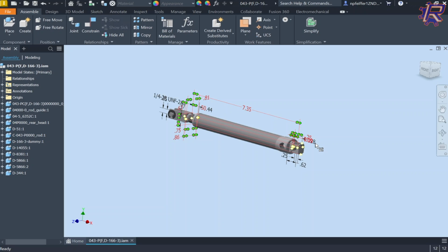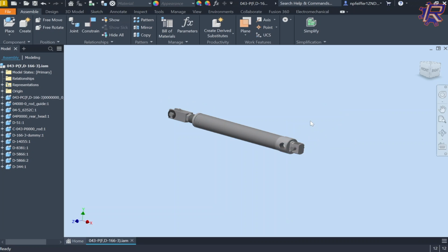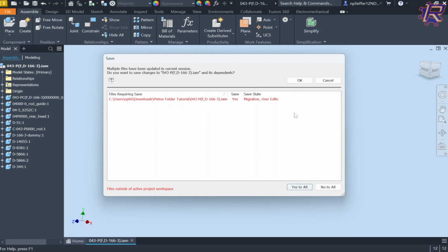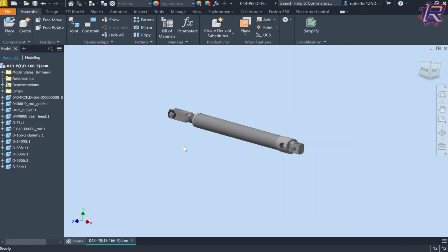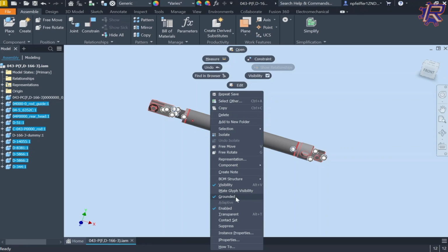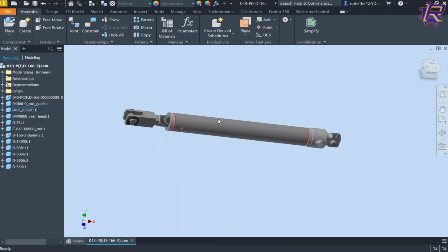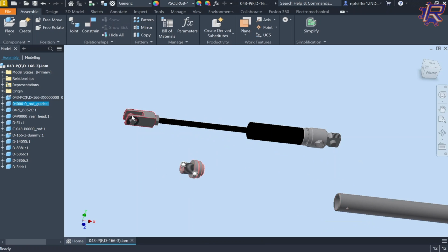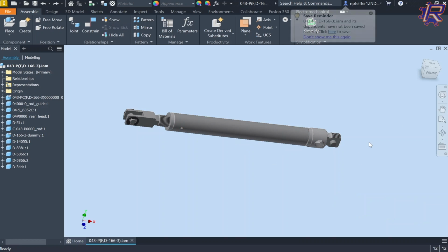by shift clicking and delete and delete. And I'm going to save that. At the moment, this piston is currently grounded. If I unground it, you'll notice that it's not actually constrained. The piston can't actually move properly. And we're going to need to set up our piston so we can constrain it properly.